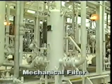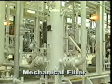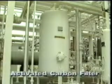Filtering can also be done before the lean amine stream enters the contactor. For good solution control, solid matter down to the 10 to 15 micron size should be removed. Some sweetening units will have filters on both the rich and lean amine streams.